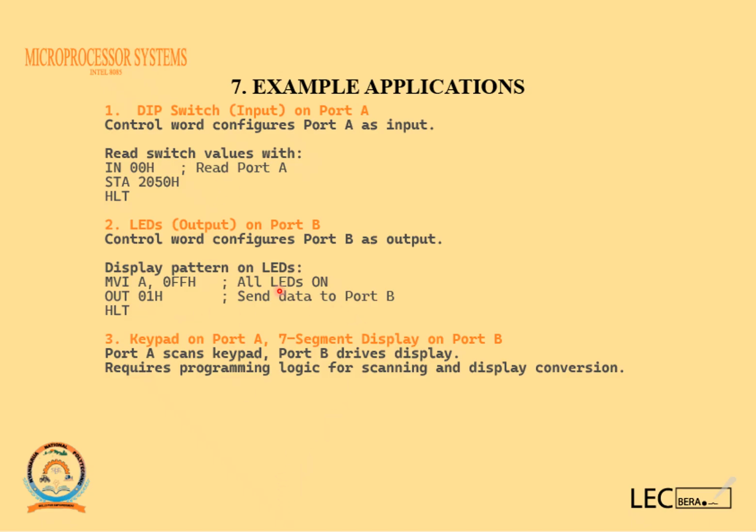What about when it comes to a keypad on port A and a 7-segment display on port B? Port A scans the keypad, port B drives the display. This requires programming logic for scanning and display conversion.